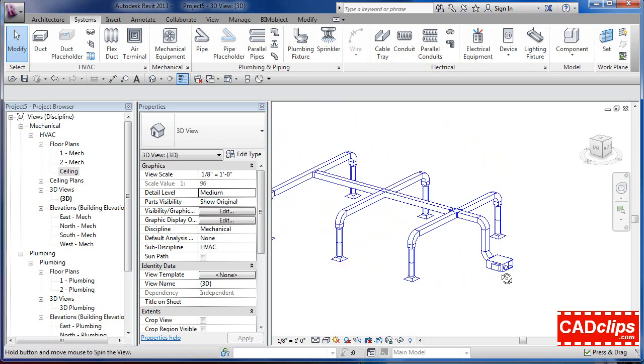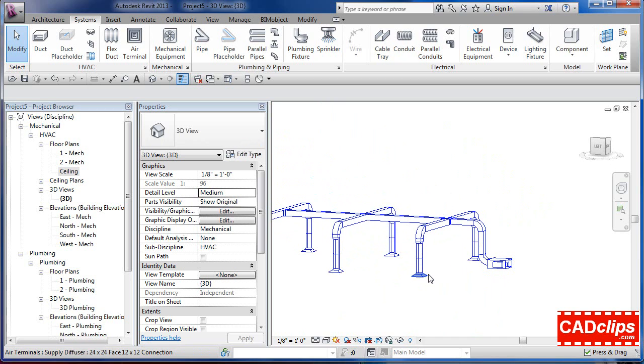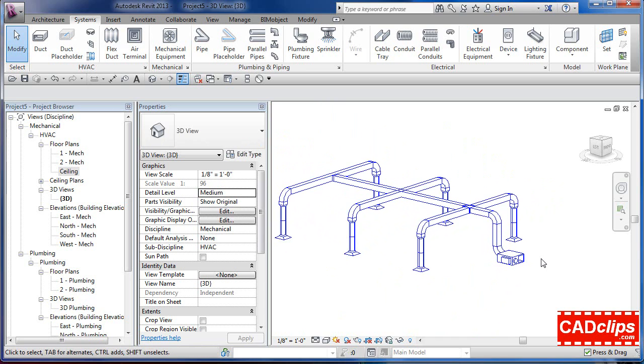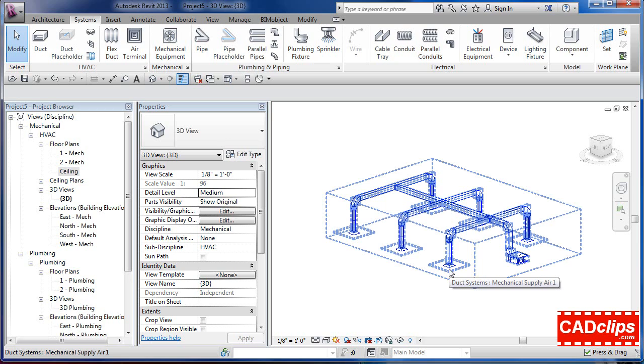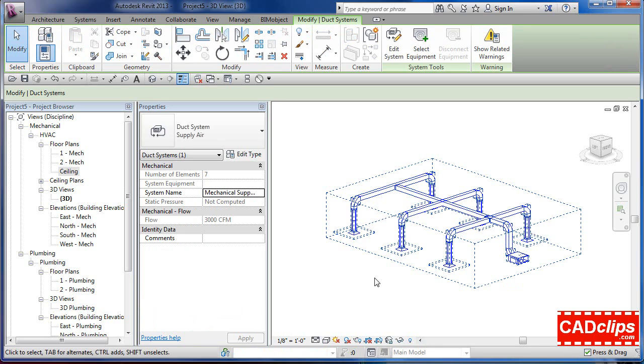But that's really not what we wanted because that would go up into the next floor and back down again. So I hit OK anyway just to prove that we can do it. So watch what happens. I'm going to hover, tab, tab. See, tabbing now, it goes to the next connection. Hover once and then tab once, tab again, tab again, picks the whole thing. When it's all highlighted, sometimes you have to do 4 or 5 tabs, then pick.